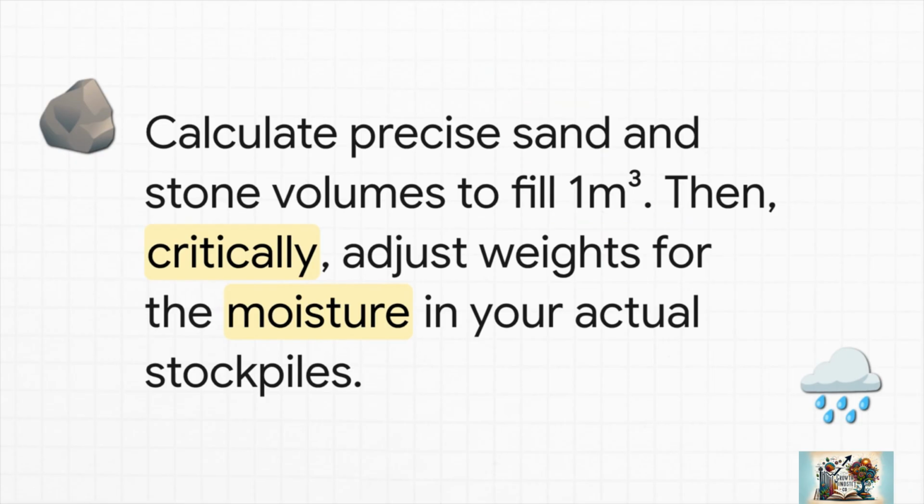And finally, we get to the aggregates. It calculates the precise volumes of sand and coarse aggregate needed to fill up exactly 1 cubic meter. Then, and this is the most critical step for real-world batching, it adjusts all the weights to account for the moisture that is actually in your stockpiles at the plant.